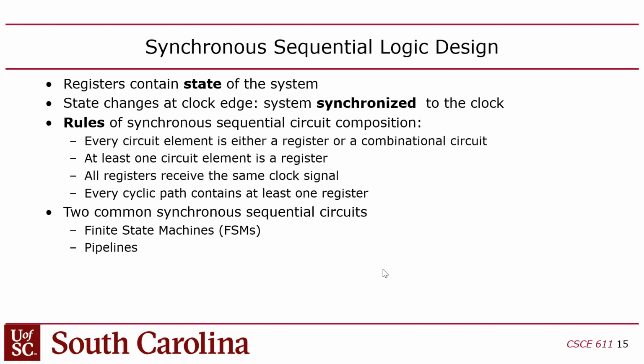Okay, so use registers. In our case, we're using registers for pipelining, right? And the program counter. So we've got a program counter and we've got pipeline registers. The pipeline registers are designed to break the execution of each instruction into 3 stages. The idea is that if you executed instructions in one cycle, you would have a very long chain of things that have to happen for each instruction, right?